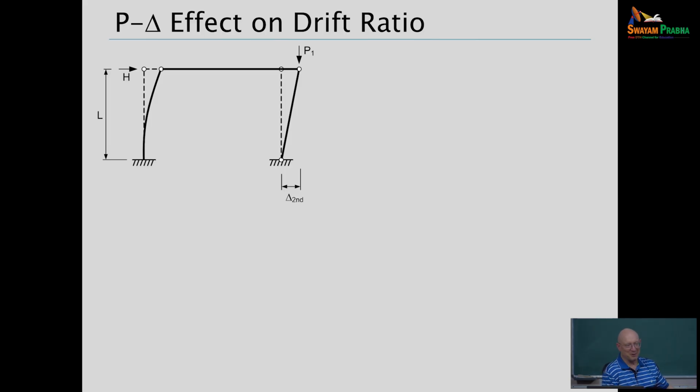It has no stability. It would just fall over, right? So that means it's leaning on the lateral load resisting system, represented by our cantilever on the left. And for purposes of our initial discussion here, let's say that the only significant gravity load or vertical load on the system is P1.